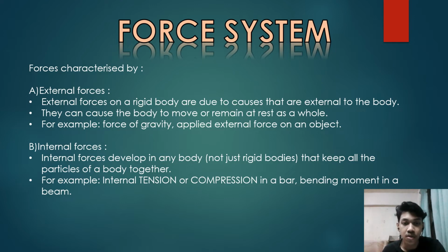The second type is the internal force, which can develop in any body, not just a rigid body, and keeps all the particles of the body together. Examples of internal forces include internal tension or compression in a bar, bending moment in a beam, and others.